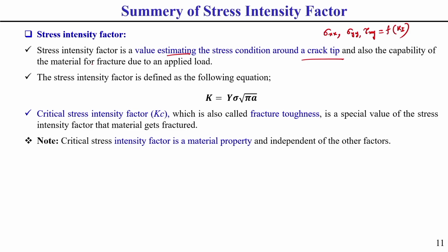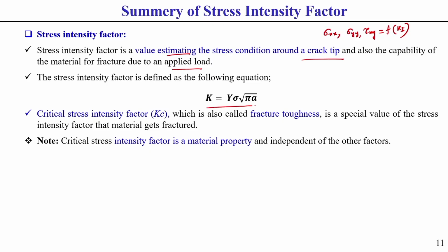That is why I have written that the stress intensity factor is a value which estimates the stress condition around a crack tip, and it is also the capability of the material for fracture due to an applied load. This stress intensity factor also represents when the fracture of a material takes place for a particular load. How? Everything we will discuss in detail. The stress intensity factor, I have already shown, is represented as Y sigma square root of pi a. How its unit comes, I will also discuss in detail.